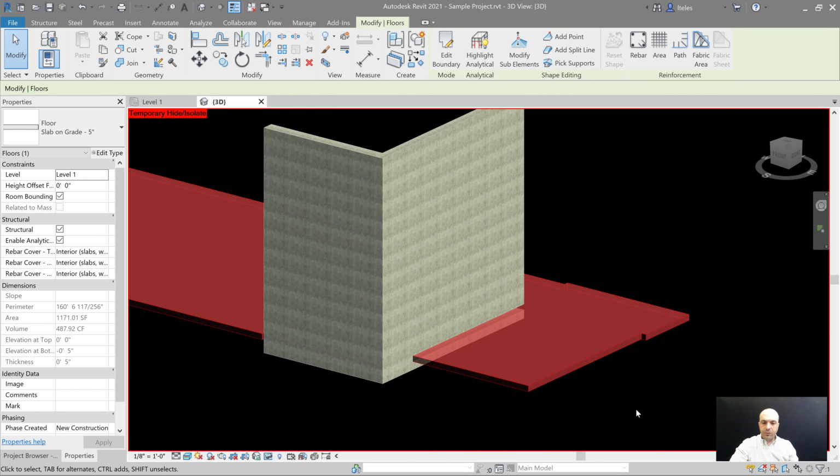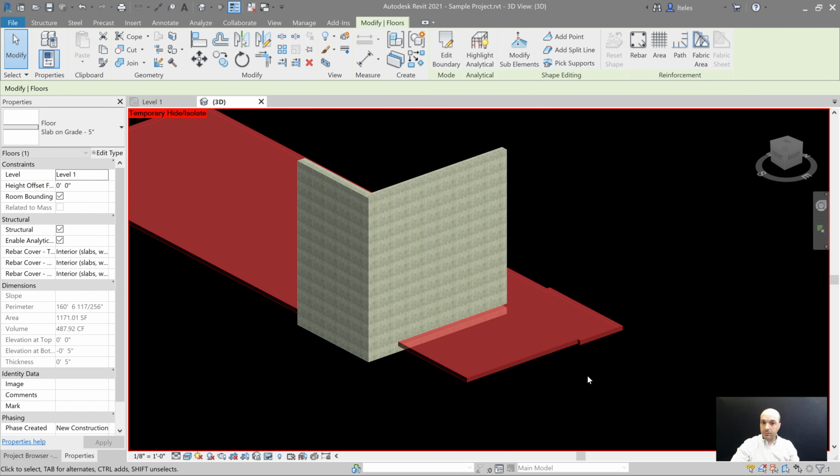Now, if we see what Revit is doing, what Revit considers important, when we used our join geometry, it automatically assumed that that floor was more important than that wall. You now need to communicate back to Revit which element is truly most important. Right now the floor is slicing through that wall right there, but we know, based on construction practice, that this wall will be there first, so this join needs to switch.